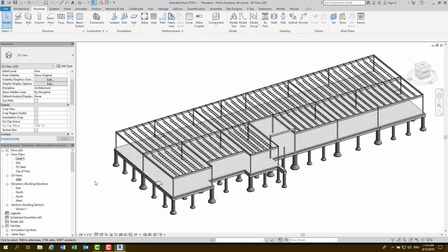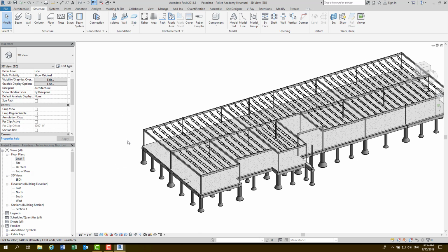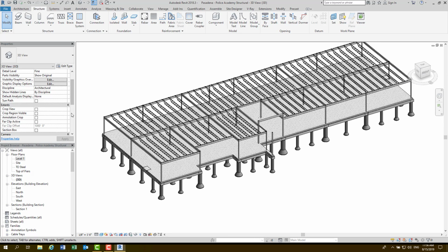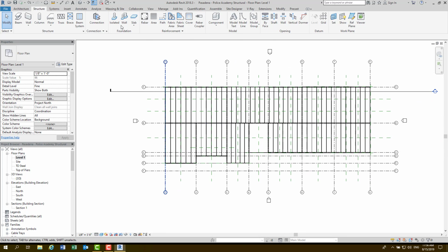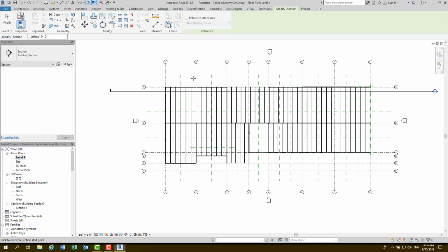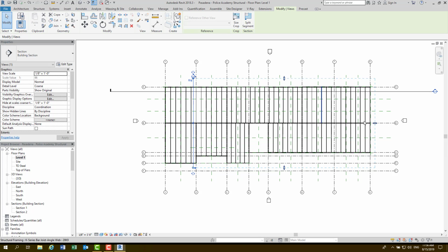We got structural steel in there. The next thing is to start looking at some of the walls and maybe some of these other steel members, making sure that they don't have different upper offsets that we need to take into account. One last thing before I go for this particular episode. Go ahead and save. I'm going to cut a section plane or a section cut because I want to take a look. Usually whenever you do this, it's going to automatically take it as far out as it will go with whatever 3D objects you have. I don't want to do that.